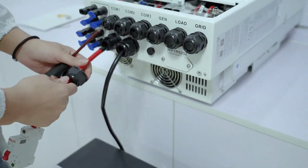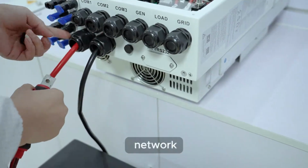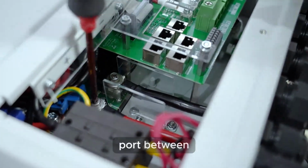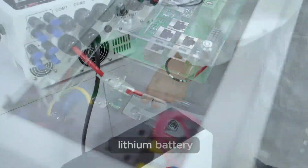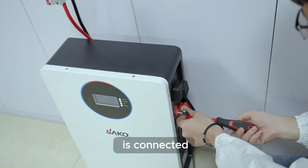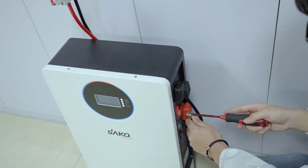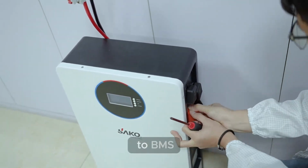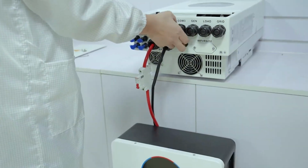Step 3. Use the network connection cable to insert the communication port between the inverter and the lithium battery. The lithium battery is connected to the CAN/RS485 port, and the inverter is connected to the BMS port.